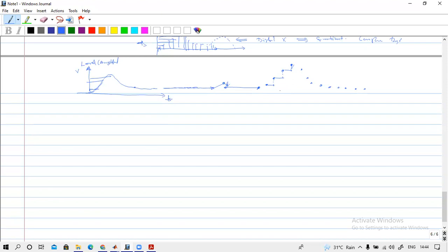You can see that here we have this kind of continuous signal, and as output of this switch, this is the input. The input is a continuous signal, and as output we get some samples, or voltage values. So this is a discrete signal. By using this switch, we have converted this signal into a discrete signal. In other words, we have collected some samples of this continuous signal. This is the first sample.